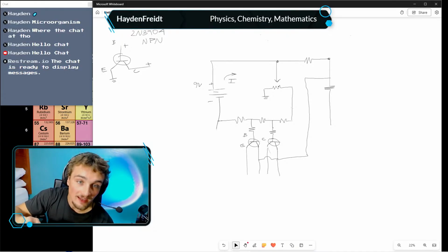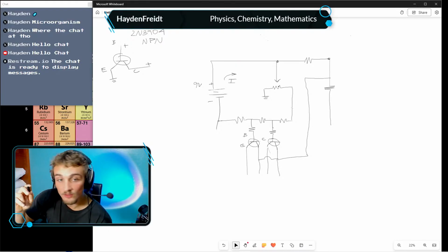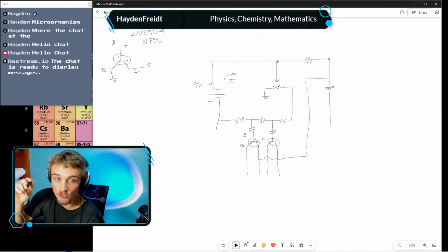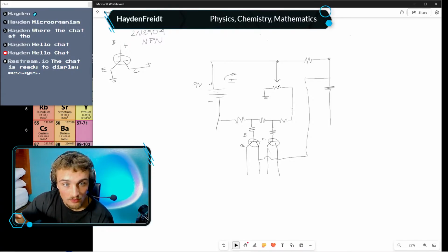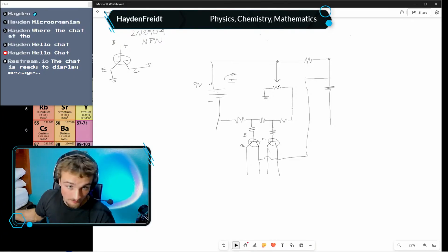So for the purpose of that, it's beneficial to put another resistor in the place of that solid state resistor incorporated into the potentiometer, you feel? That's another thing to do, because that resistor is going to essentially be from 9 volts to ground, so 9 volts across like 1,000 ohms is okay, right? Because, okay, let's just do this.